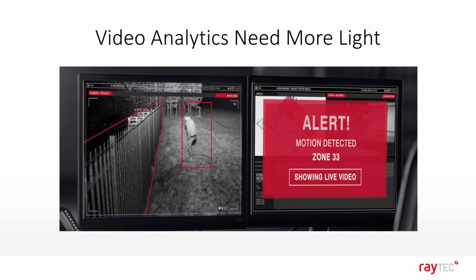And also on the dark areas of the image, depending on what kind of intelligence you're using, because it's dark, it'll become noisy, and it might see that noise as a kind of movement. So it might trigger cross-line detection. It might think that somebody's crossing the line. It might classify something incorrectly, that kind of thing. So it's very important that you have the correct light level for the analytics, whether that be infrared or white light.